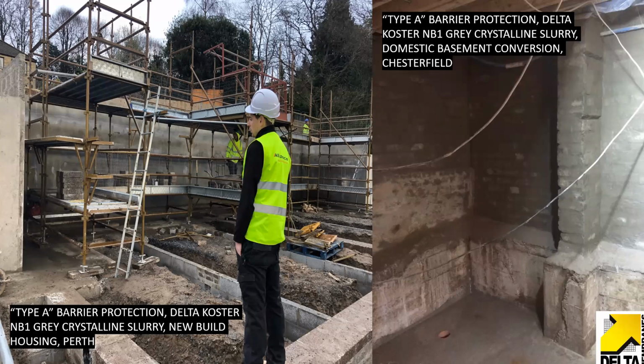So that we can do what we call lock down the structure from the inside using these products which grow in, if you like, crystallize within the pores of the concrete, brickwork, masonry, whatever it is. So they're type A systems on the negative face, the internal face. The outside face of the basement is called the positive face. That's where we have membranes. On the inside, we're always going to use cement-based products that grow into the structure and become monolithic with it, yeah? So those are type A products on the inside.